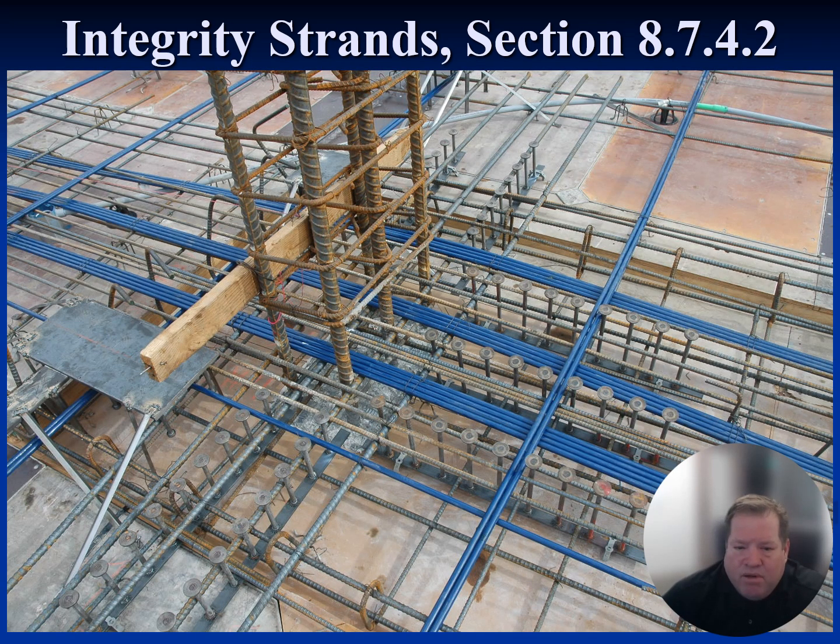This is another example of that situation. You can see the banded tendons going right through the column core, which is great, but these strands are here, not even close to the column, and these strands are way over there.